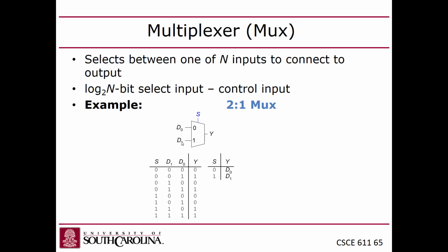You can use multiplexers to have multiple sources of data enter one place. For example, and you guys have seen this in 212, when you do an add instruction, you can either add 2 registers together or you can add 1 register and a constant. Well, that second input has a multiplexer that allows you to choose whether you're adding a register value or a constant as the second operand. You guys with me? So these come up, these are very fundamental.